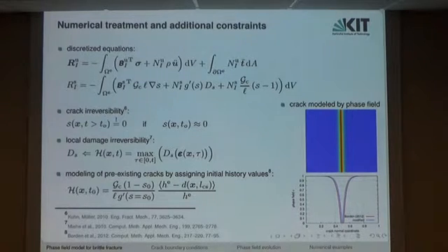To prevent crack healing, a Dirichlet boundary condition is imposed where the material is fully broken. Alternatively, if we use the phase field to describe damage, a non-negative damage rate can be enforced by replacing the crack driving energy Ds by a history field, which includes the maximum crack driving energy obtained in history.